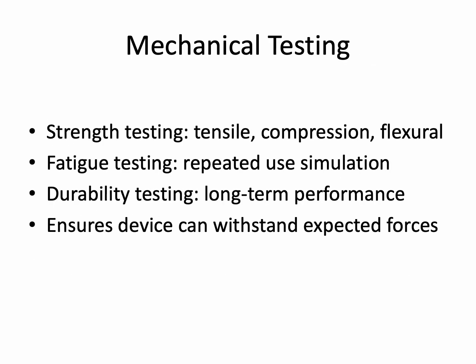Mechanical testing verifies that devices can endure the forces encountered during intended use. Strength testing evaluates tensile, compression, and flexural capabilities. Fatigue testing simulates repeated use to identify potential failure points, while durability testing assesses long-term performance and longevity. Comprehensive mechanical testing ensures device reliability, supports safety claims, and satisfies regulatory evidence requirements for higher-risk classifications.